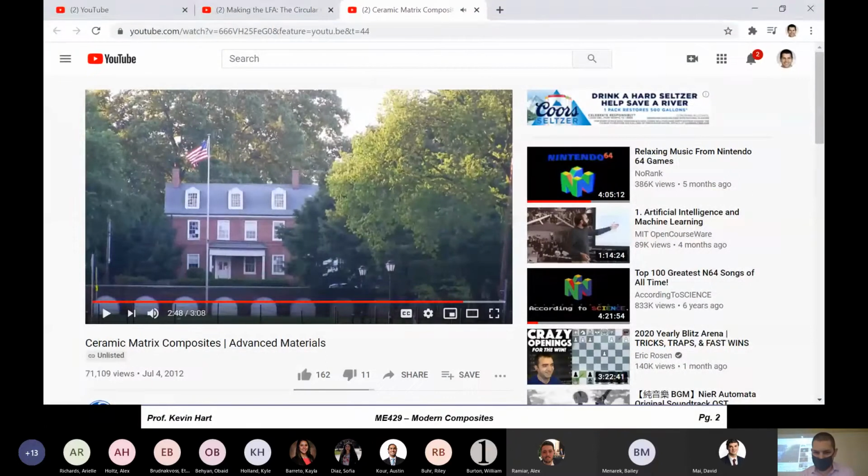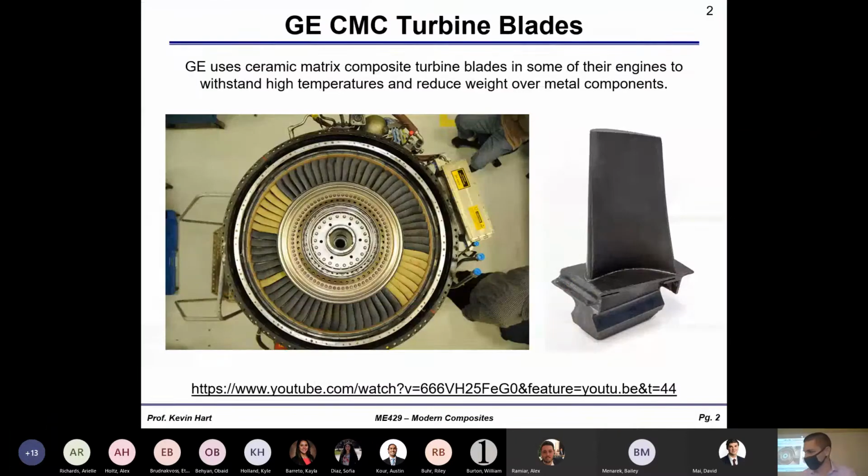Okay, so there's cool thing number 2. High temperature ceramic turbine blades. They're talking mostly about the shroud in that video, but the production for the blades is probably very similar. So yeah, the blades obviously look something like this. And then around the outside of the blades, on the perimeter of this engine, they're talking about the shroud, which is the ceramic layer on the outside of the blades.